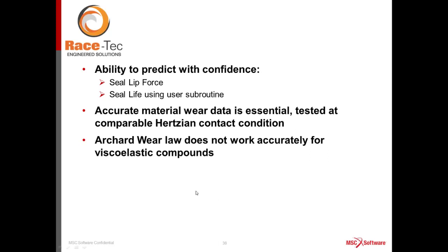However, you need to be very accurate in your material data for your wear conditions and ensure that you've tested a comparable Hertzian contact condition. Simply using the standard pin-on-disc type materials for something in a rotary motion is not going to give you the right result. We found by experience that the standard wear law is not really sufficiently accurate for viscoelastic compounds, and that we've worked on reviewing our own version of this with some external testing.